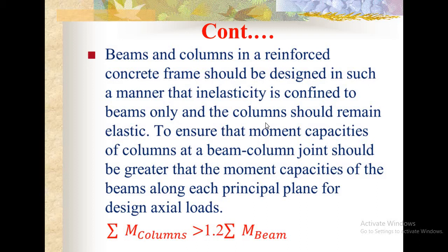To ensure this, the moment capacities of the columns at the beam-column joint should be greater than the moment capacities of the beams along each principal plane for the design axial load.